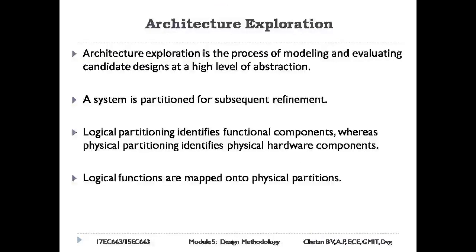Architecture exploration. Architecture exploration is the process of modeling and evaluating candidate designs at a high level of abstraction. A system is partitioned for subsequent refinement. Logical partitioning identifies functional components, whereas physical partitioning identifies physical hardware components. Logical functions are mapped onto physical partitions. The physical partitions can include processor cores, accelerators, memories, and I/O controllers.